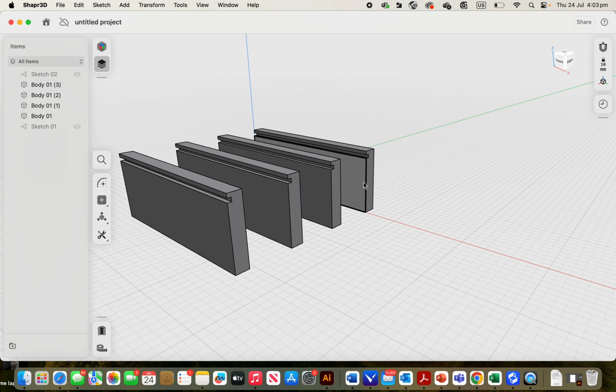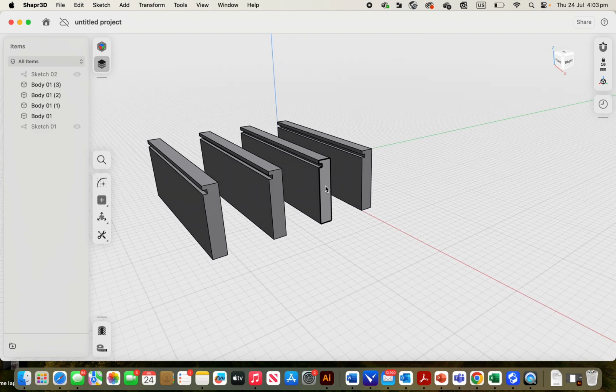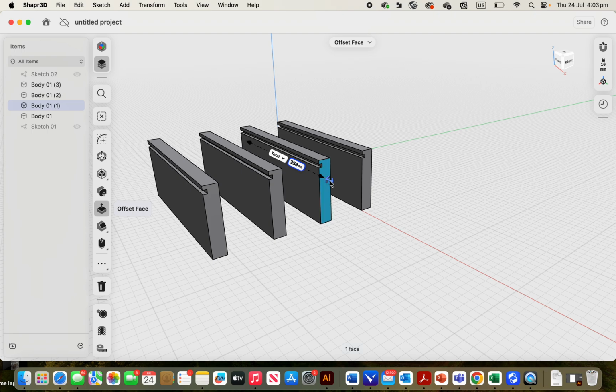What we're going to do is focus on these 2 over here, and change them to 150 millimeter lengths. So we're going to have to take 100 millimeters off them. What we need to do that is rotate it so you can see the edges of the timber like this. Put your cursor on it and click it. Now you can tell you've got these blue arrows again, and it says it's 250 millimeters in length.